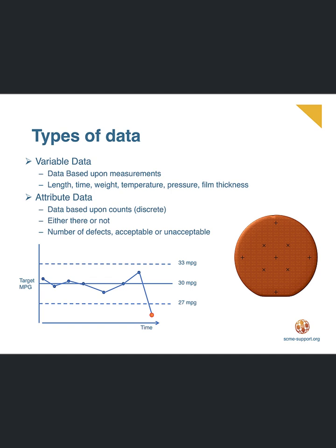looking for 4-leaf clovers in a field of clover. It has 4 leaves or it doesn't. It's a cracked egg or it isn't. In the manufacturing of microsystems, variable data is more commonly used and more efficient at detecting out-of-control, OOC, processes than attribute data. Variable data is continuous and quantitative, meaning that a variable measure can conceptually take on any value in any given interval. Common variables measured include length, yield, time, weight, temperature, pressure, line width, and film thickness.